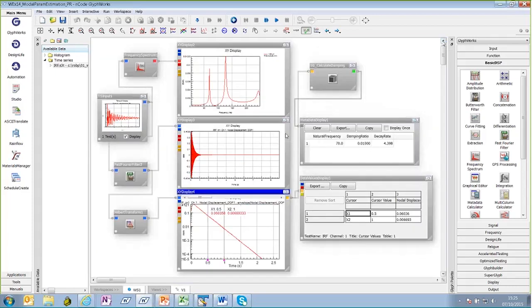That gives us the data for the drop-off at that point and the frequency step. And then you can use that directly to measure the damping ratio and also the decay rate of that signal. So that you can get the Q factor for that, and then that can be used in any measurements or future calculations you need the damping for. So quite a good use for that envelope function. Although you can do that from the frequency domain, this gives you a much more accurate answer.